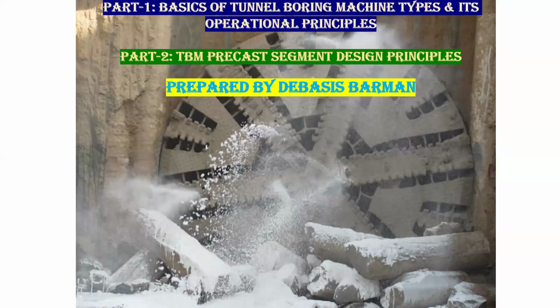The difference between conventional tunneling and TBM tunneling is that TBM tunneling is mechanized tunneling. In conventional tunneling, we make an excavation either by drill and blasting or by mechanical excavation, and then install the supports. There are two types of support, a primary support and a final support, and there are other intermediate activities also. So it's a very slow and lengthy process.